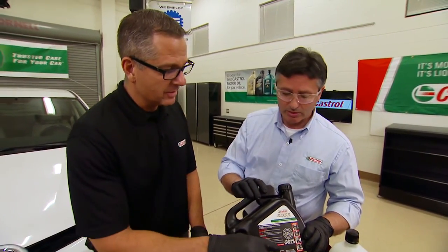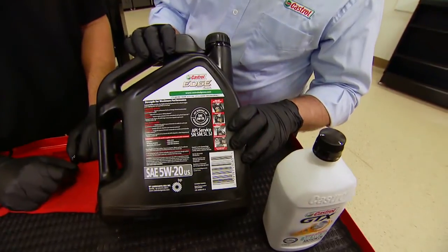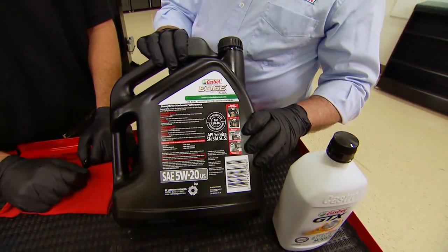Now I was always told also that the latest and greatest alphabetically, doesn't it go up higher as the better oil, or is that just a myth? No, that's correct, John. Actually, the very first oils were API SA oils from the 1930s, 1940s. We've since progressed to the current category of API SN, which is a very highly engineered engine oil, which has to match the performance requirements of today's engines, the high performance engines that are on the road. So the categories get tougher as we go through historically.